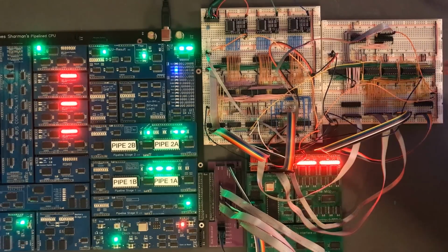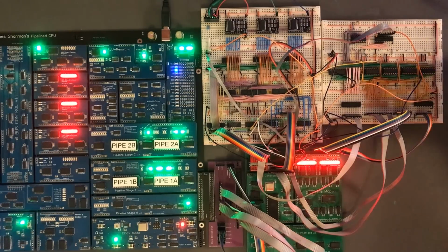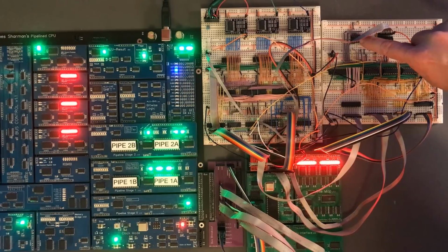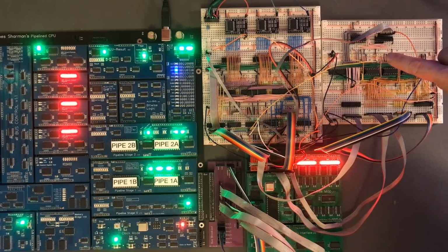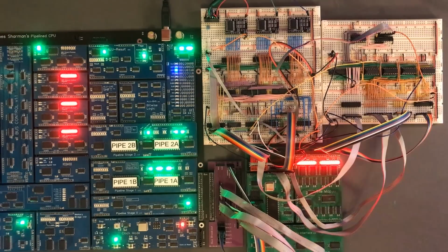The tile data is actually a very simple circuit, at least compared to a lot of the other circuits we've been doing for the VGA. We've got a memory chip, a set of multiplexers that are going to be taking the incoming address from either the address data bus or various bit swizzling between the index and the XY position within the tile. We've got an output multiplexer that's slicing up the 8 bits into two 4-bit colors. And then we've got some latches just for handling the timing.